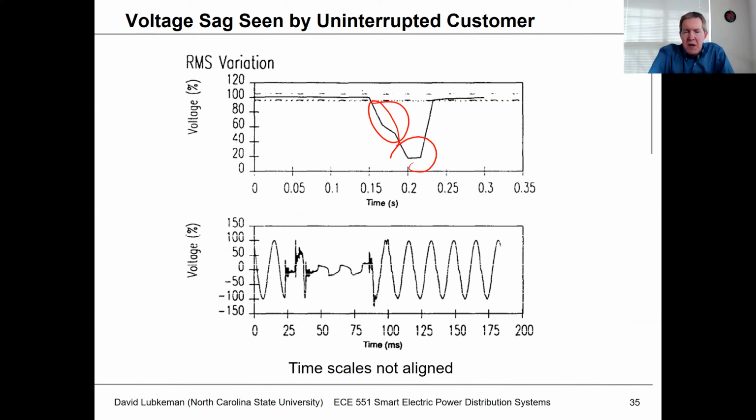But what the time domain waveform actually looks like looks like this right here. It's really kind of distorted looking. And even when we get into steady state a little bit, it's not even a sine wave anymore. This is because a fault's not actually a perfect zero impedance. A fault's not even a perfect low impedance. A lot of these faults have kind of time varying resistance. And because of that, the current gets pretty erratic, and as a result, the voltage can get kind of erratic. So it's not a nice sine waveform that you see on the unfaulted phase necessarily.